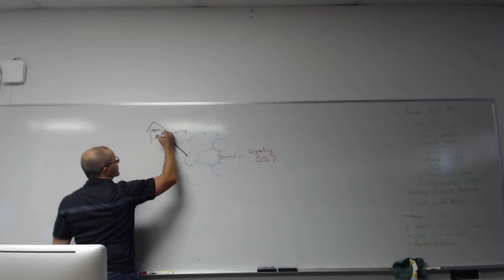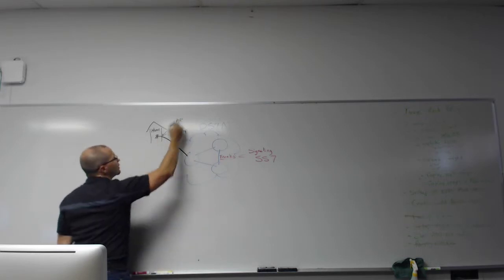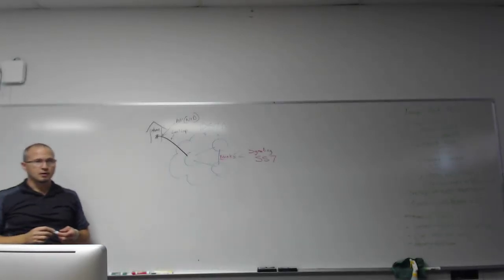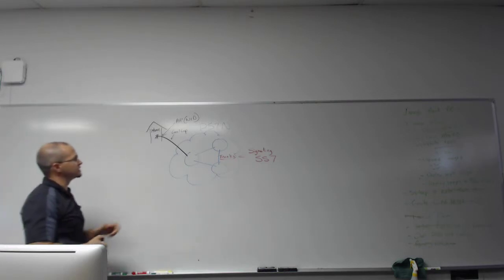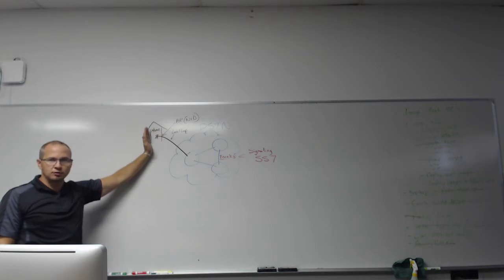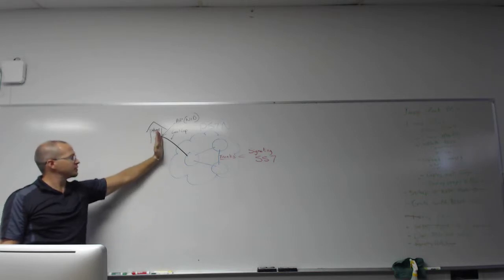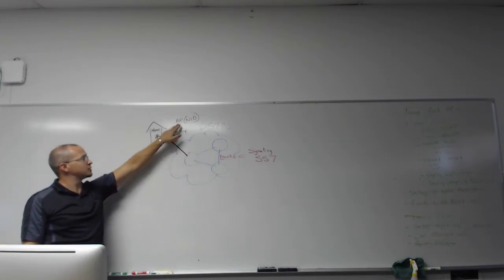This connection right here at the house is called a point of presence, or the network interface device, NID. And I don't think that's a term on our sheet, but we can add that. Point of presence. This is where the responsibility of the telephone company is relinquished inside your house to the owner of the house. So this is your responsibility inside the home, everything from the point of where they attach to your house and underground or on the telephone pole back to the telephone company. That's their responsibility. So that's why they call it the point of presence.